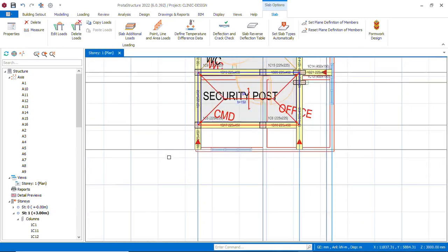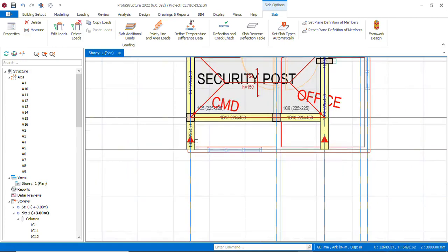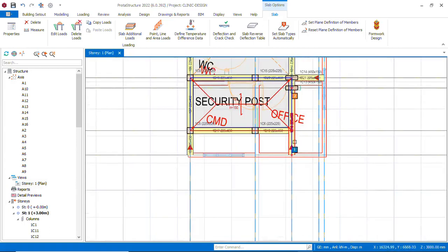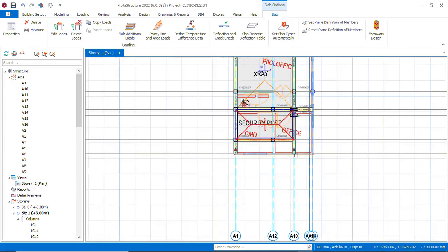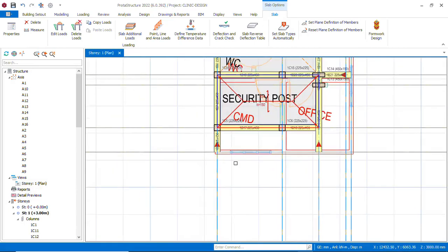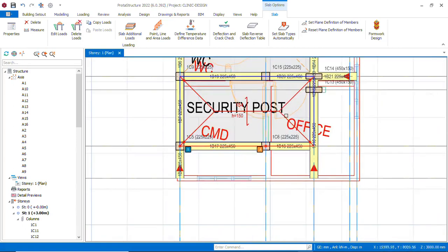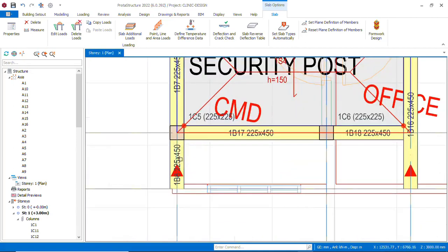a beam. Alternatively, if I don't want, maybe the whole of here will just be a pure cantilever slab. That will put a wall load. I will put a cantilever load on it. Okay. Down to this place. Okay. And I'm not doing that. Let me just put a beam and then put the wall load on the beam.